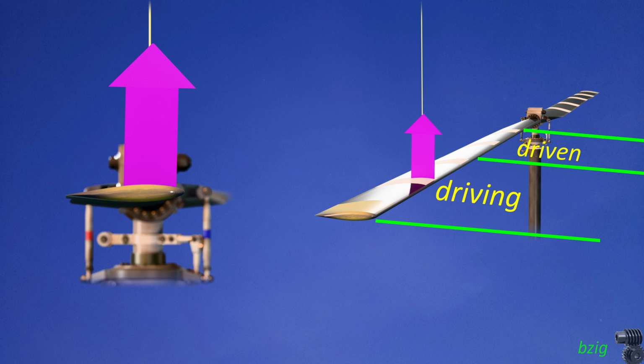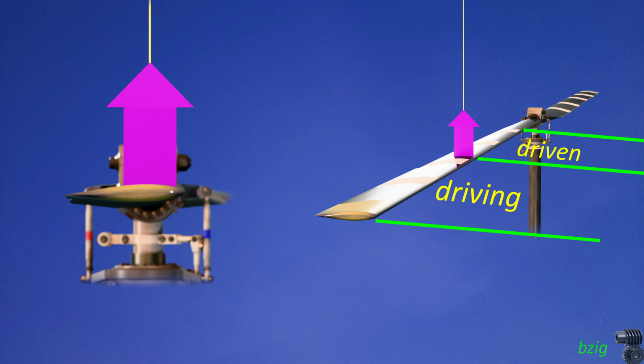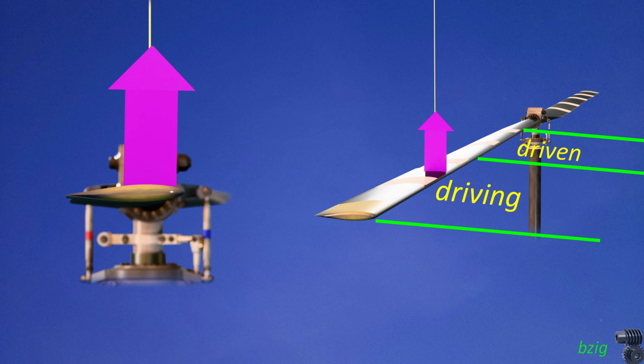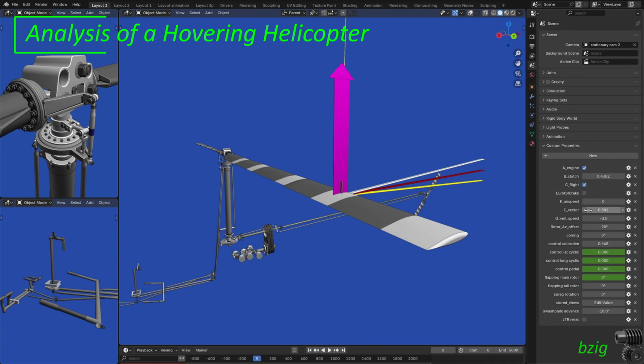As I slide the vector in and out, it becomes apparent the driving region is outboard and the driven region is inboard. And I should mention again, this is a hovering analysis, and these regions change somewhat in forward flight. Showing this total aerodynamic force vector was the intent of this video, but now we can get to the fun stuff and talk about the aerodynamic theory it took to simulate this on the screen.